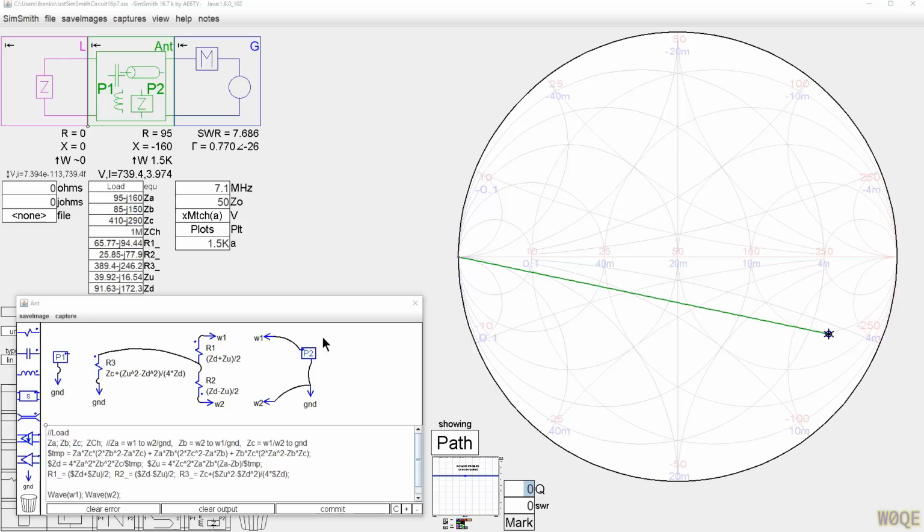And we have a network analyzer here, or impedance analyzer, or whatever. We have one side of it connected to a ground stake or some ground screen to measure; basically it's intended to be at this same impedance. This point to this point should be a low impedance. And we're going to make three measurements. Those three measurements are going to be ZA, ZB, and ZC.